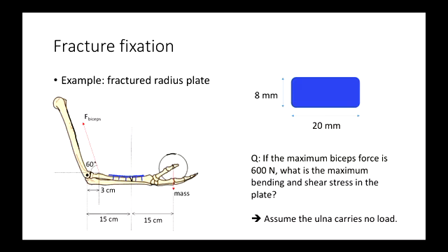Solving for M, you get M equals 52 newtons. So, if we divide by 9.8, just to see how much mass it's lifting, that comes to 5.3 kilogram. So it's interesting, right, that if you generate 600 newtons of force at your forearm, all you lift is 5 kilo.